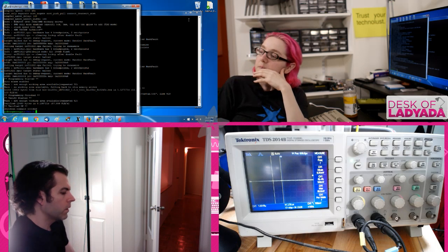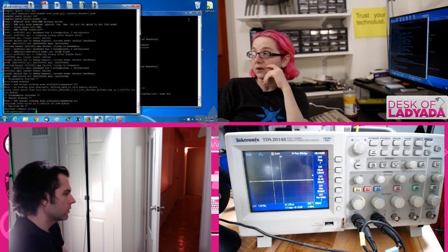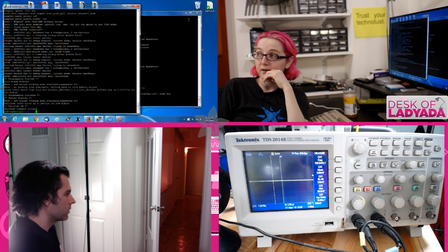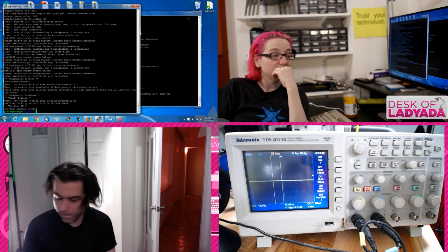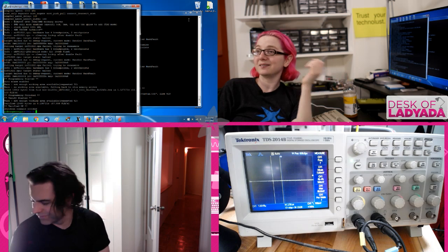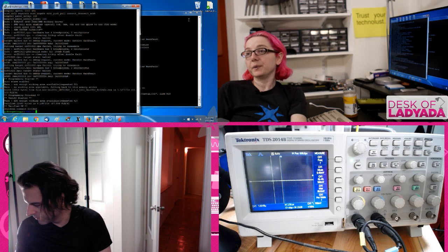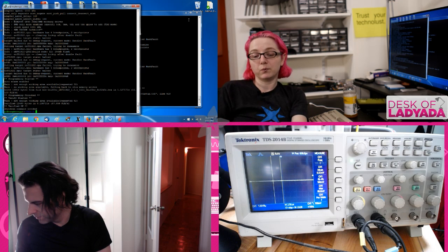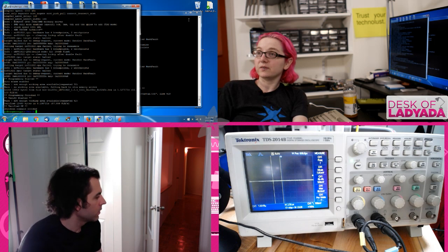Can you use a Pi 0 for this? You could. Yeah, there's no reason you couldn't use a Pi 0 as an OpenOCD project. That would have been a cool thing for the Hackaday project. Someone could still enter that in as a project somewhere. I think that ended 2 days ago. There's another one, but there's a new project. There's always. But you could totally make a cool $5 OpenOCD remote thing. You just plug in a Wi-Fi adapter. It shows up on Bonjour as OpenOCD.local.